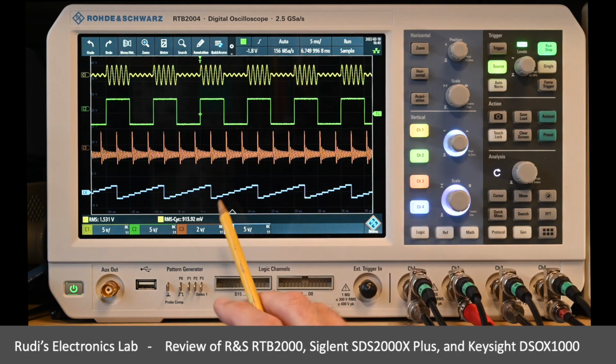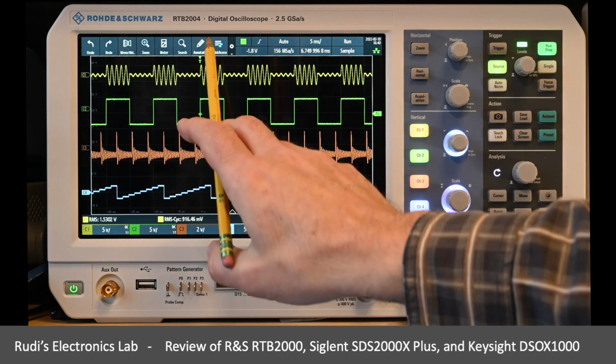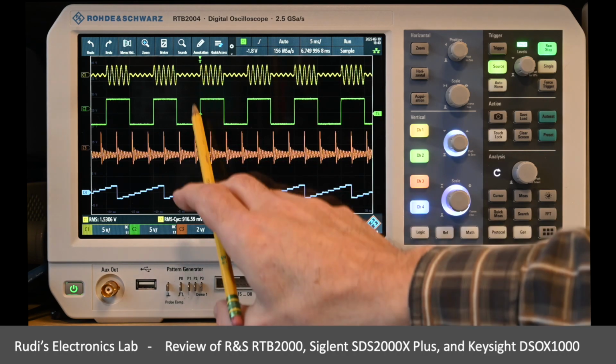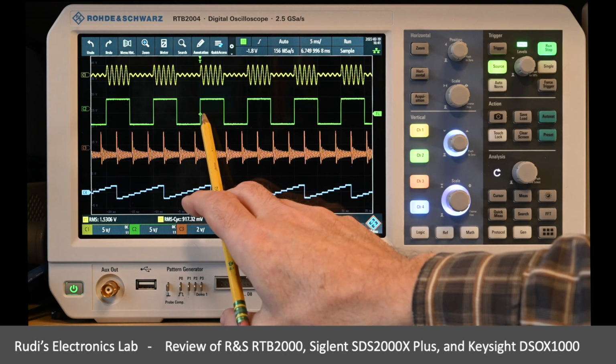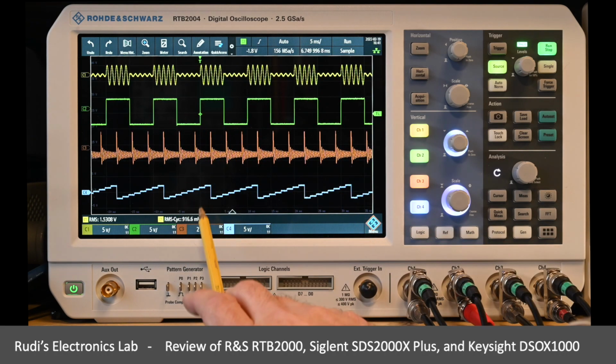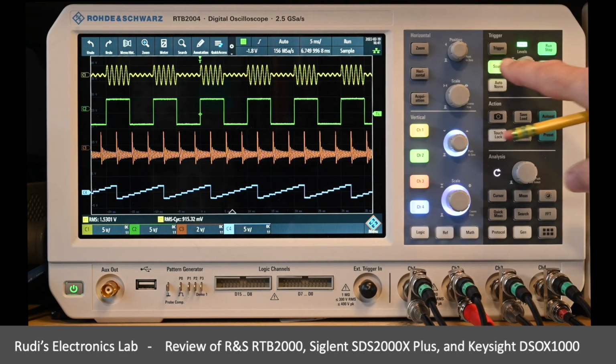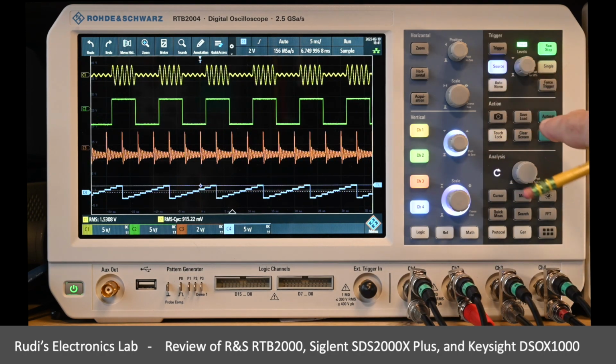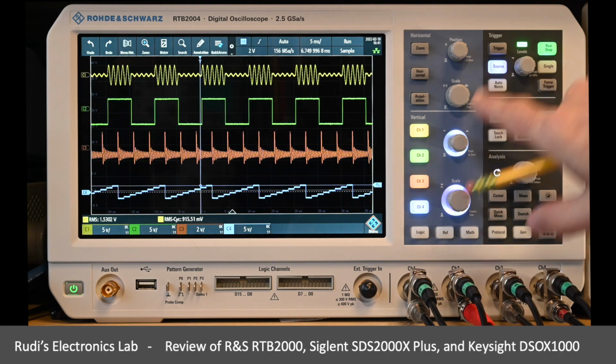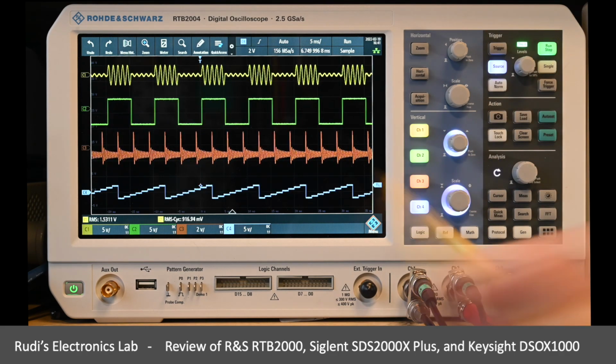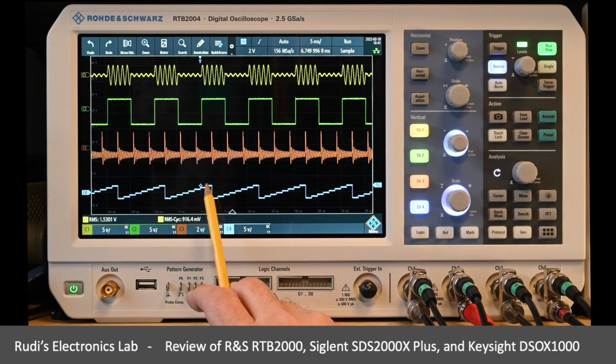And I'm now going to trigger on the ARP function. So right now I was just triggering here on this block wave, so it always triggers nicely and stable. Now I'm going to trigger down here, so let me change my trigger source. This button here gets blue, this all gets blue, also tells me that this is selected. Now it's actually picking one of the plateaus over here.